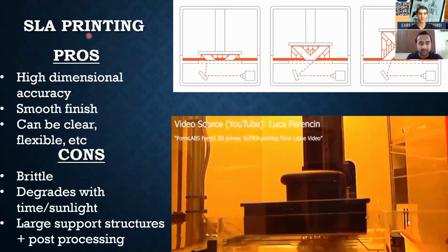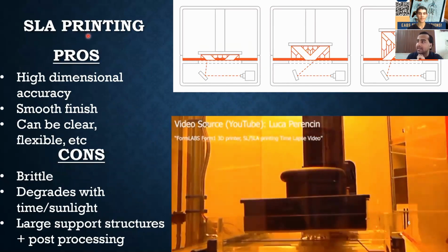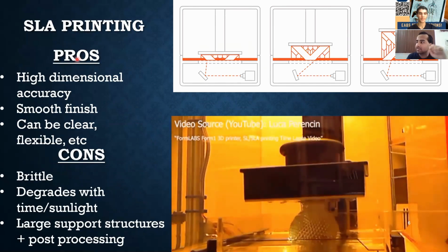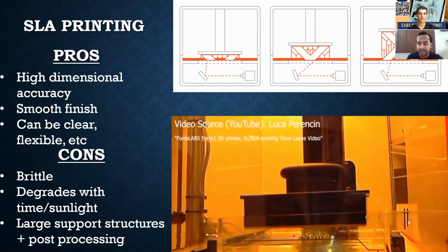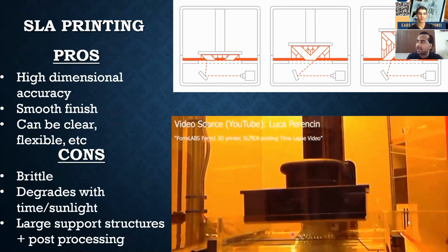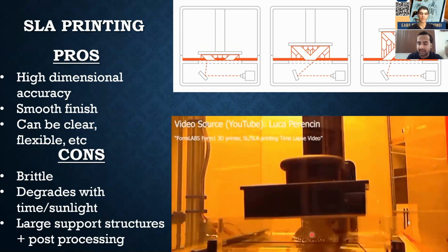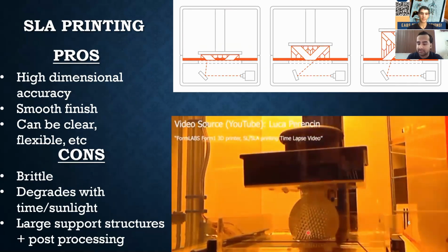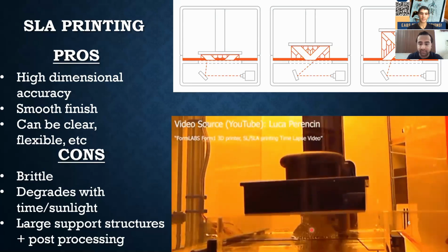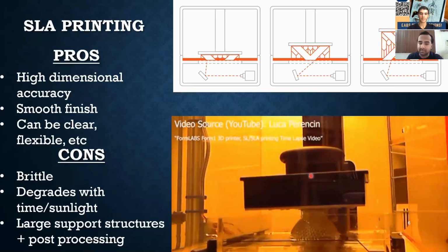It's called SLA printing. Now, SLA printing is also additive, but instead of fusing together a bunch of powders, it works by having this sort of bed of photoactive resin. And what happens is the layer goes over each layer, and then selectively cures it, usually using, for example, UV radiation, and then it just sort of builds from the bottom up.